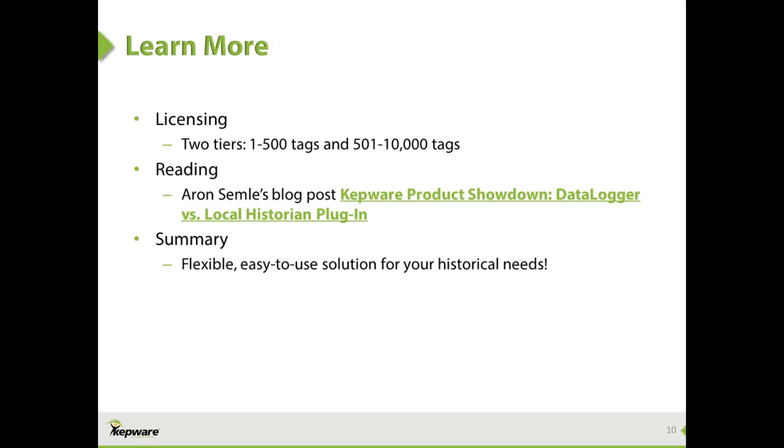Is the historian capable of performing standard math functions on the data, average, min, and max? From Eric, that is a question. The answer to that would be no. You would need another product. We have our advanced tags product that can do those mathematical functions, or you would do that in your HDA client software.